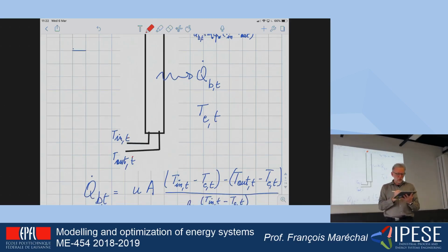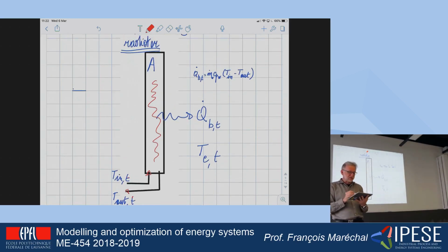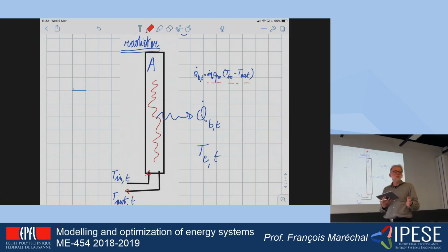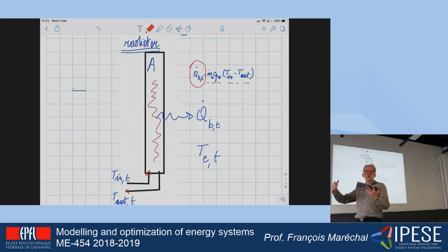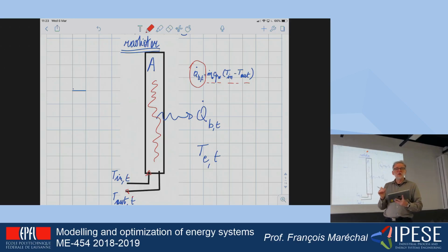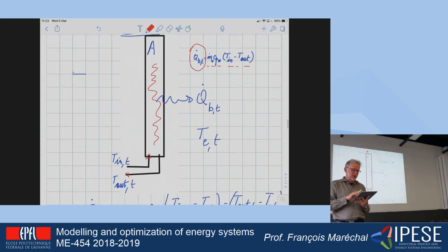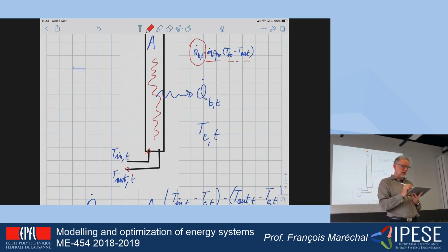So it means that on the one hand, I will have a flow of water that is going to enter and that is going to leave. It is going to do the heat exchange here, okay, and that is going to see the temperature of the room. Which means that now I can represent, on the one hand, the heat that is supplied, which is in fact the heat that is delivered here by the water that is circulating at a given flow in the radiator, okay, and that is going to make a temperature difference. So I'm obtaining, therefore, the amount of heat that is delivered by the radiators in the room, and by extension in the building, if I'm assuming that the building is at constant temperature or needs to be at a given constant temperature. Okay, so now I have the heat load that is needed, that is supplied by the water with a given flow of water and two temperatures.